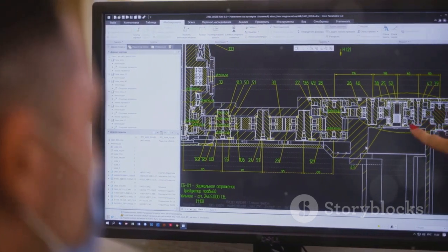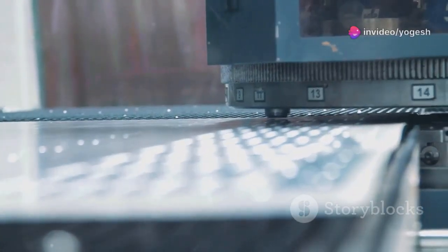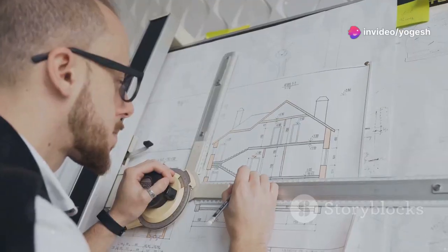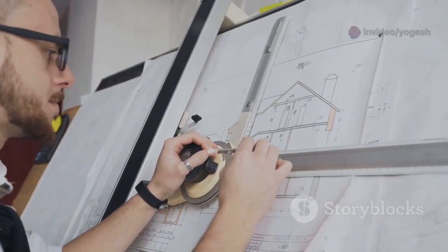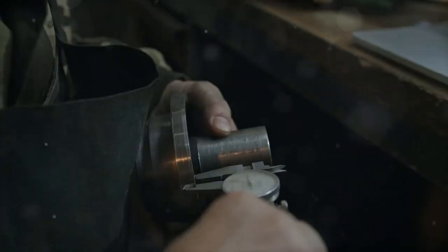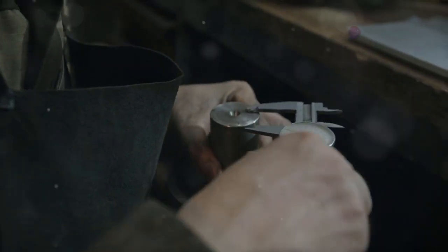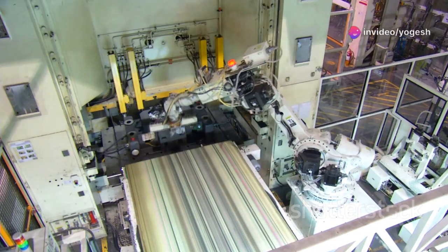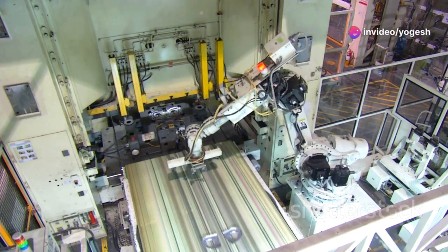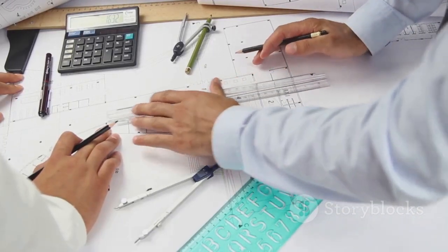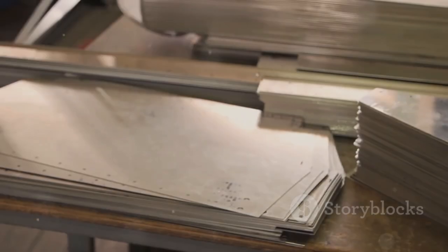Flange sizing is also critical. Too short, and the tooling can't grip. Too long, and you waste material. Minimum flange height should be 4 times the thickness plus the bend radius. For a 2 mm sheet with a 2 mm radius, that's at least 10 mm. Proper hole and flange design ensures accurate, easy manufacturing. Simple adjustments here save time and prevent costly errors.